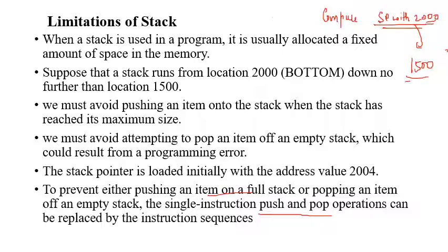Since 1500 is the last address of the stack, as soon as this value is reached in the stack pointer, it indicates that all the stack locations are filled. So this has to throw you the error saying that the stack is full.